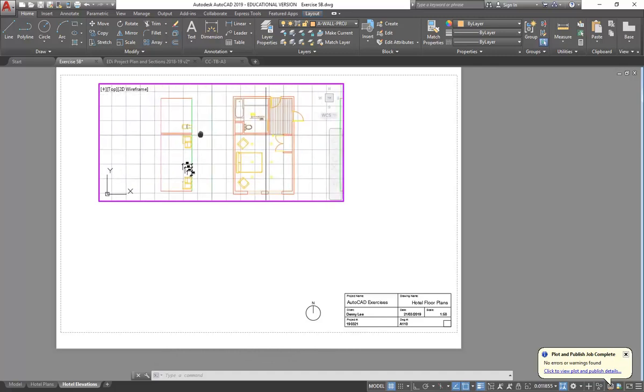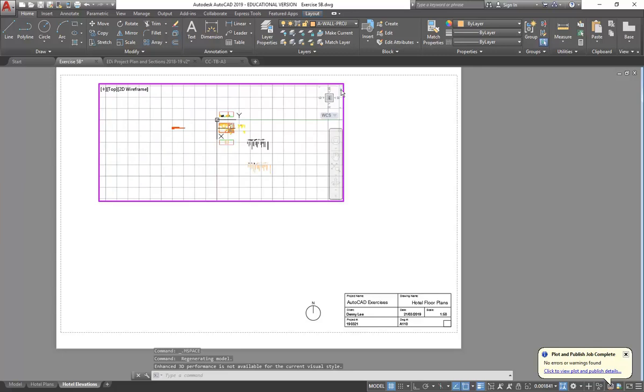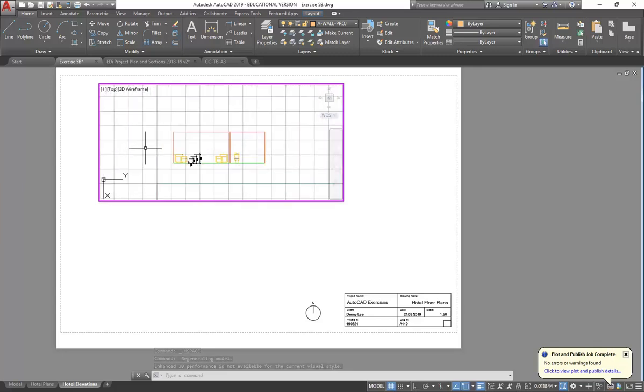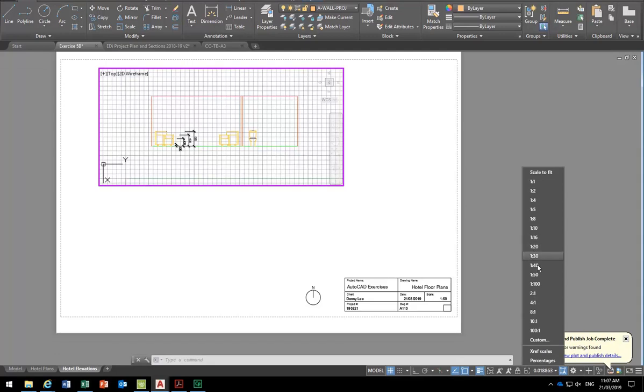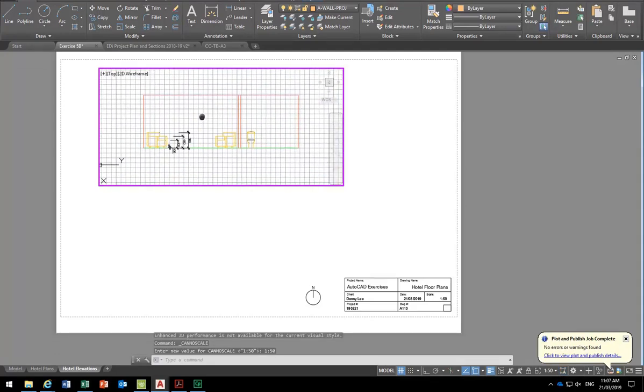So I'm zooming and panning so that you can see what I've drawn. So what's the obvious thing we need to do to get that elevation? Exactly, we've got to rotate it. So do you remember the button for that? Yeah, excellent, great. So if you're remembering that, it's in this compass or view cube area, but it doesn't come up until you move your cursor there. So you've got to have that view cube, but then move your cursor up and to the right, and you'll see, it's hard to see, but there are two little arrows there, and they rotate the whole view. So clicking there, you can see it's rotated the right way, and then you can zoom like before, position it, and afterwards set the scale to 150. It's pretty close to that already, and there we are.